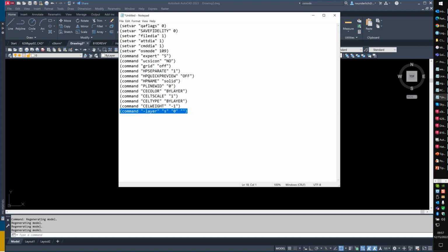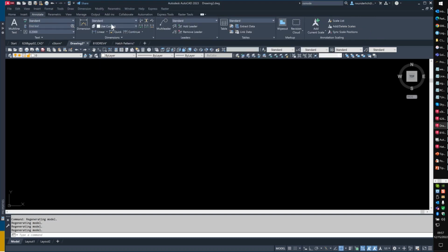Do you use WBLOCK for clean drawings often as compared to PURGE? That depends on the level of the problem. I may just WBLOCK certain things out, but if you are using WBLOCK, anything that's ambient in your environment, in other words, whatever your current layer, line type, text style, dimension style, multi-leader style, and table styles are set to, all get embedded into that.